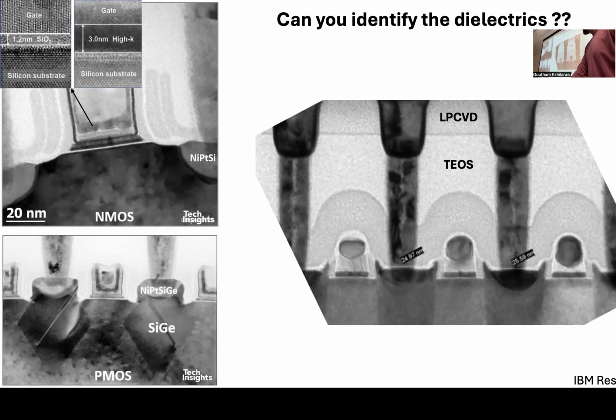Yeah. So this CMOS is generally a lower K dielectric. It has, other than silicon and oxygen, other elements also, and based on the growing conditions, it also tends to be slightly porous, right? So this one is generally lower K. While the dielectric here is ALD, it's the best kind of dielectric you can grow, right? That's why it tends to be very high K.